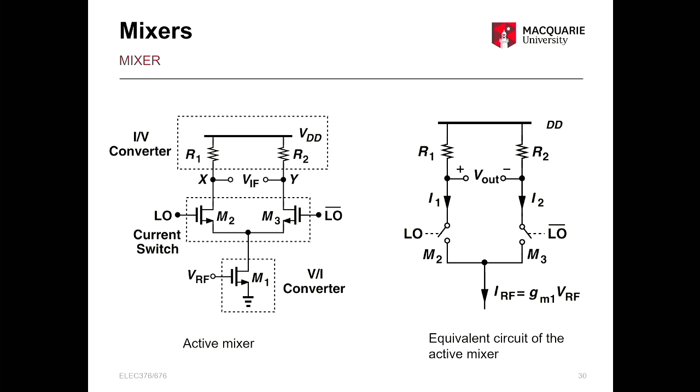So you're adding two signals and giving them into the nonlinear device. That is an OR, yeah. So you're adding cos omega 1t plus cos omega 2t. You're giving that sum into the nonlinear device where it squares. So you get cos omega 1 squared and cos omega 2 squared, then cos omega 1 times cos omega 2. The multiplication is happening inside that nonlinear device. Here, you're actually multiplying.